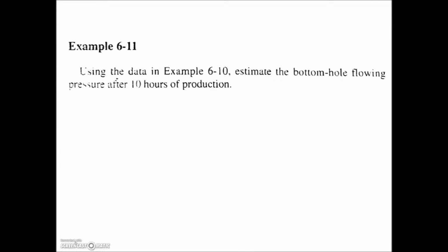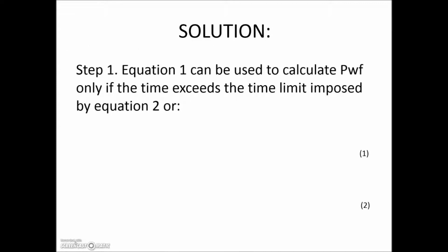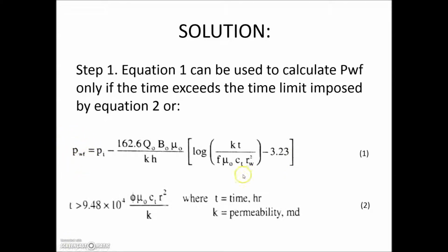As we move on to the next example, using the data in the previous example, estimate the bottom hole flowing pressure, which is Pwf, after 10 hours of production. For the solution, step 1, equation 1 can be used to calculate Pwf only if the time exceeds the time limit imposed by equation 2. This is the equation to calculate the Pwf. Next, this is the formula to calculate the t.